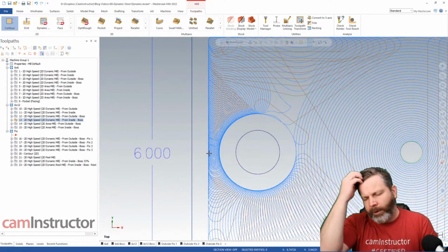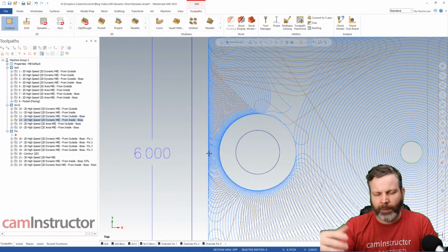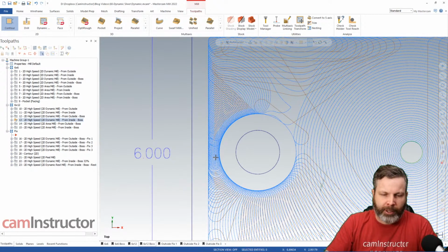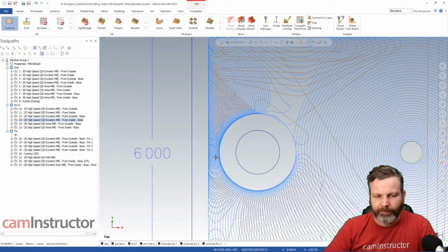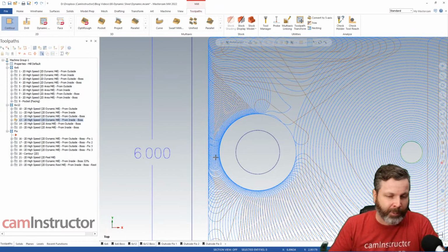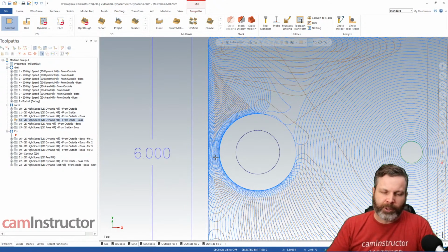Again, the argument here could be made, the 3/4 inch end mill can probably take, if we're talking 100 inches per minute here, the extra load in here. It's probably not going to care. It might bark a little bit, but for how close the machine can accelerate to get to 100 inches per minute, it probably won't. It might get to 50, 60, and on a 3/4 inch tool, it's not going to hurt it.